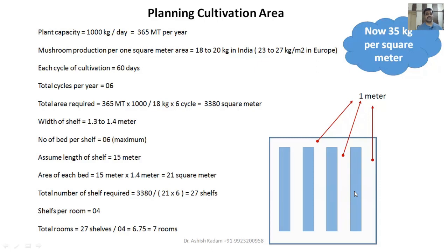So that is the reason we need to put all the calculations in place. Though it looks very simple that you can put in the ducts, you can have the AHU, you can have this planning, actually we need to do the calculations. We need to understand what velocities you require at each shelf level.